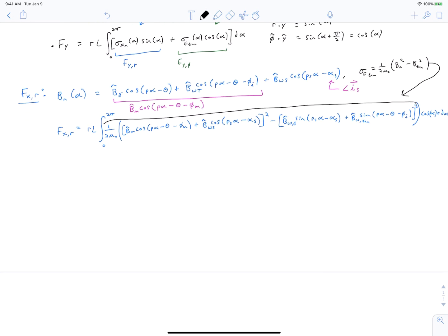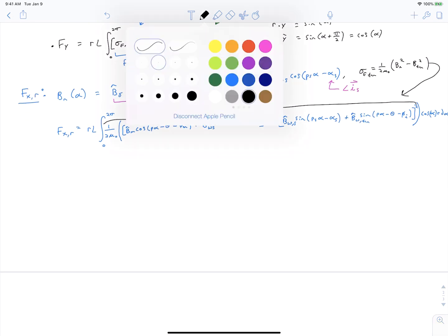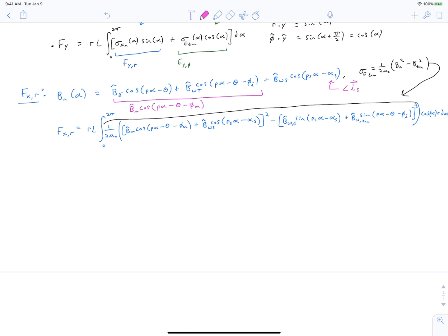The math gets complicated, so we're going to simplify it right off the bat. It turns out that while this term here is capable of creating forces, we're going to assume it's zero. It creates forces that are 2 to 3 orders of magnitude smaller than the first term. I suppose you might get into a situation with some type of bearingless motor design where you might need to come back and revisit this term. But for the purposes of this lecture, we're going to treat this as zero.